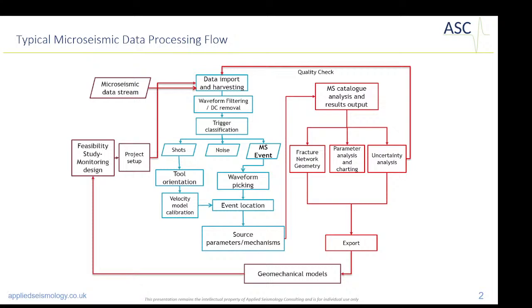Which part of the whole microseismic data processing flow are we presenting today? Well, we are discussing what would be the initial part of any microseismic or acoustic emission project, which is designing and optimizing the position of our sensors, our stations, depending on the scale we're working on, so that we can meet the objectives of our project. We will be at this initial stage, but it might also occur after the initial monitoring, because it's always a process that we can optimize.